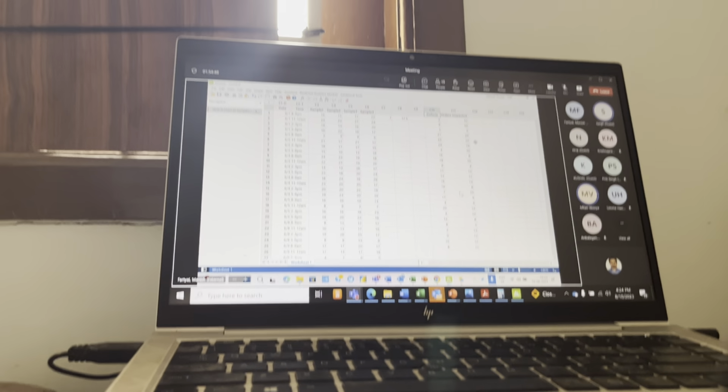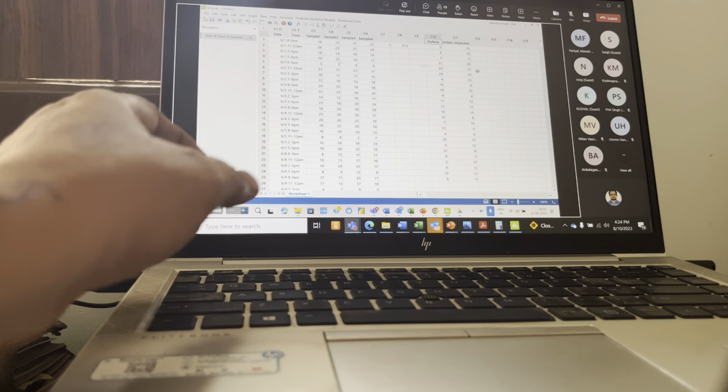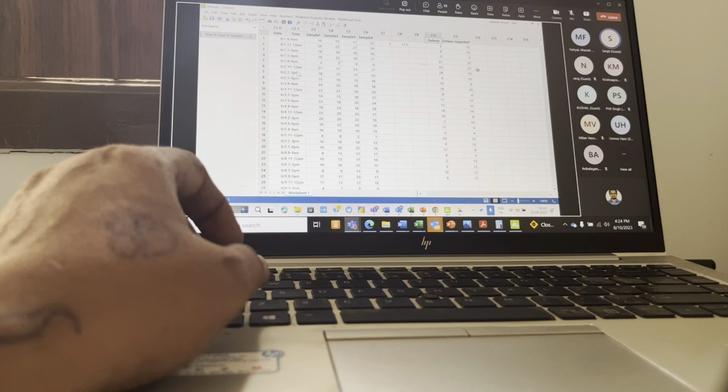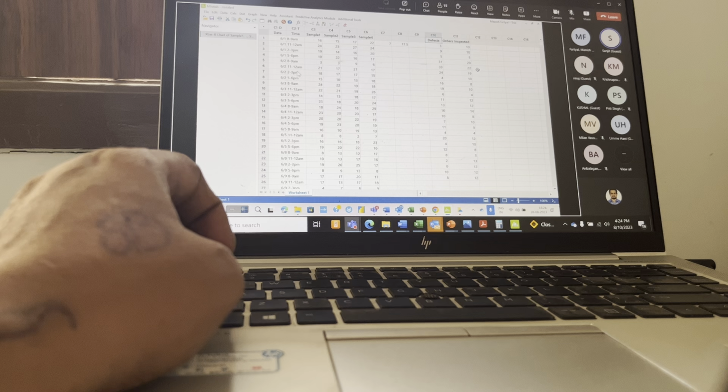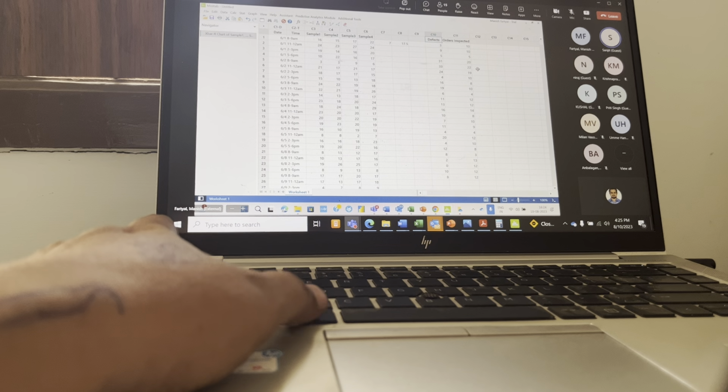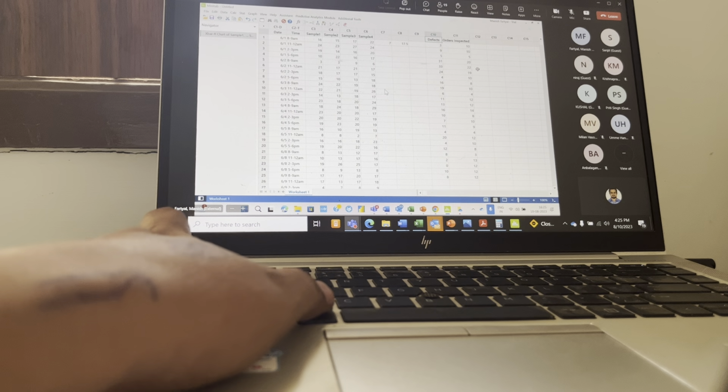So which control chart will you follow? C chart, sir. No. So when can you do C chart? Only when subgroup size is 1. Here subgroup size is more than 1. So you have to perform a U chart. Okay? Yes. Okay, do it.